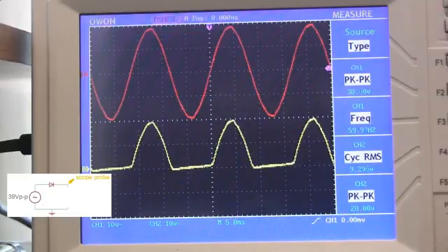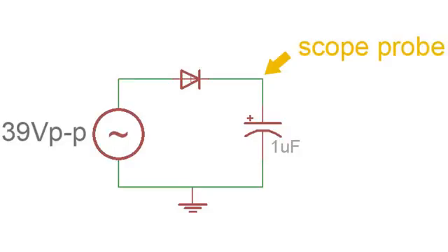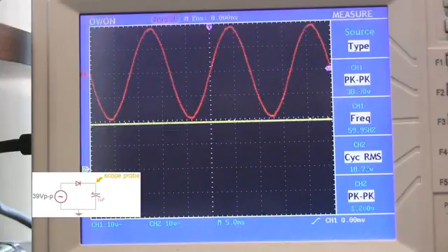Half the time you've got a weird hump-shaped voltage, and half the time you've got nothing. So you're going to need a little more stability than that if you're going to power anything useful. So, we add a capacitor here to smooth things out. I'm starting with 1 microfarad, but the more capacitance the better, because you'll have a bigger energy reservoir. That's more like it. Now I have a perfect DC output of 18.7 volts.